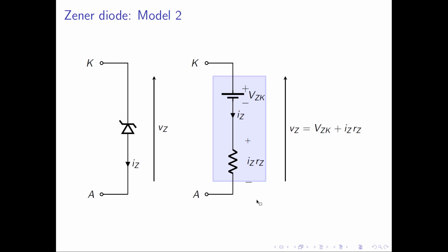Now, this diode model is slightly limited in the sense that we're not even trying to model the forward bias behavior of the device, but it would be very easy to include one of our forward bias models from the material that we looked at on switching diodes.